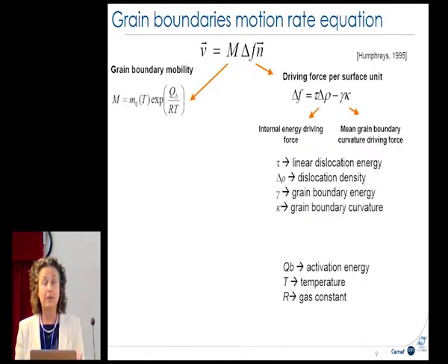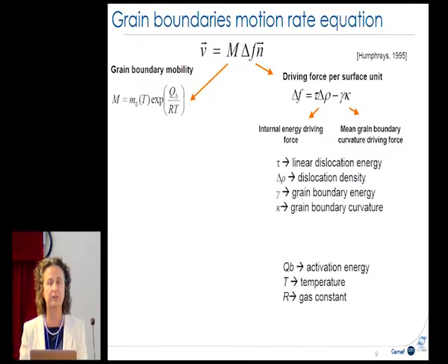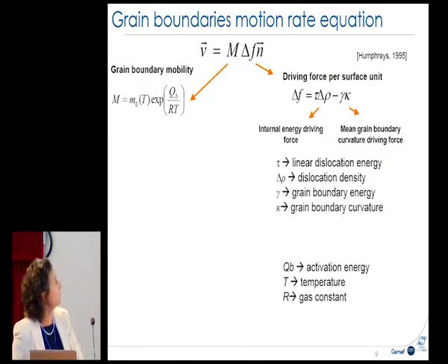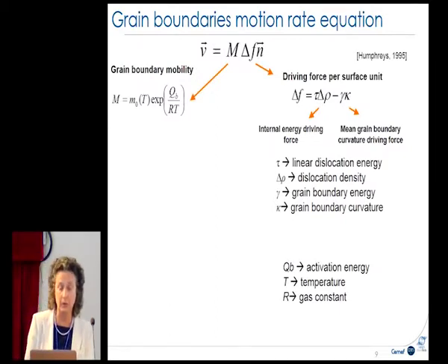So now we have to solve the convection equation. It's the moving of this level set interface following this very classical equation. If we focus on the v function here, this velocity is solved by using the classical Navier-Stokes equation. We have a lot of papers on this subject. So here, just an example.